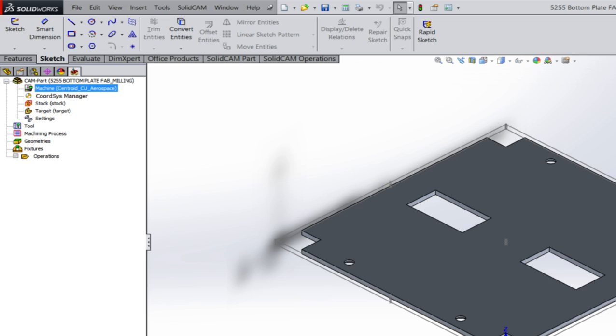When you say the stock parameters, yep. That stock is kind of the bandsaw, so it's not always the same distance. That's right. Sure. You measure approximately. So you throw a tape measure on there and get as close as you can by reading. With a tape measure, you ought to be able to get within 20 or 30 thousandths. So be accurate with your stock.